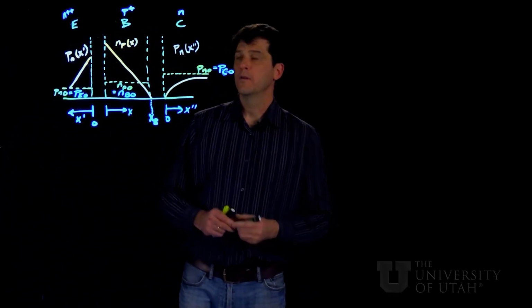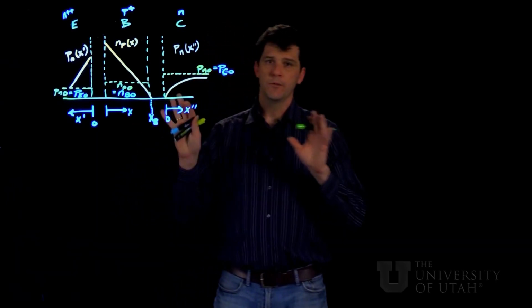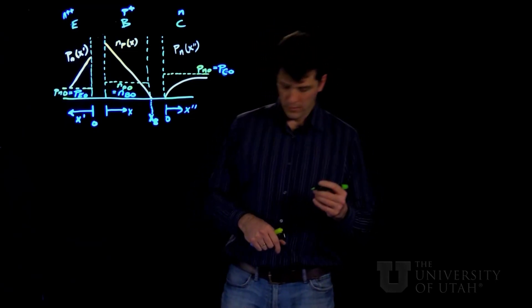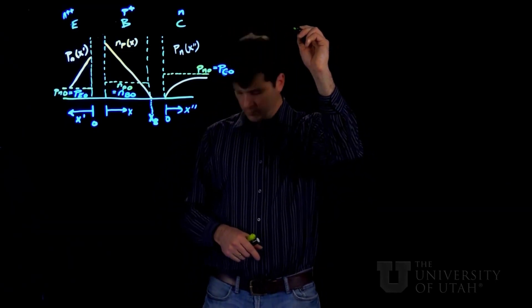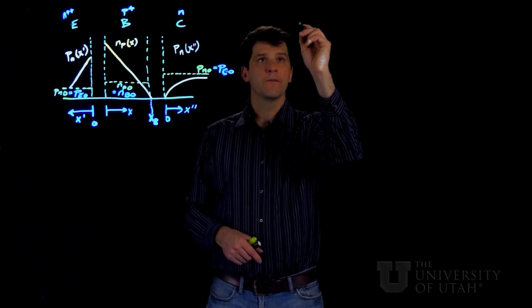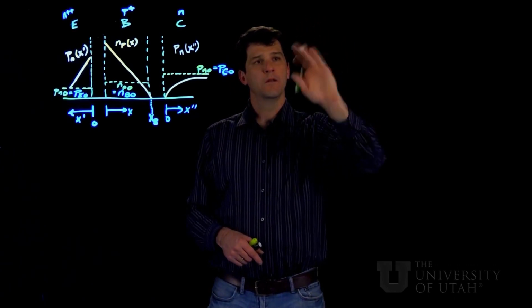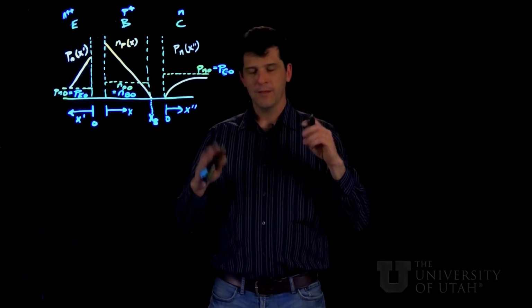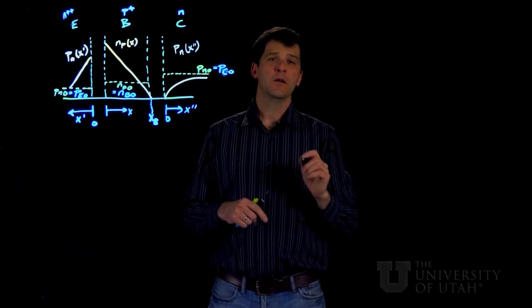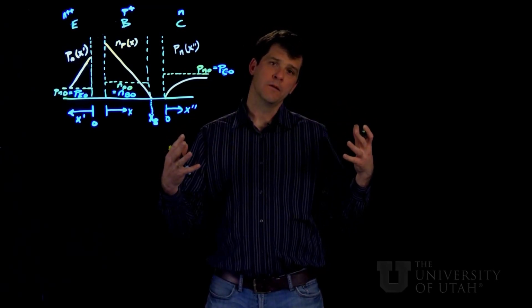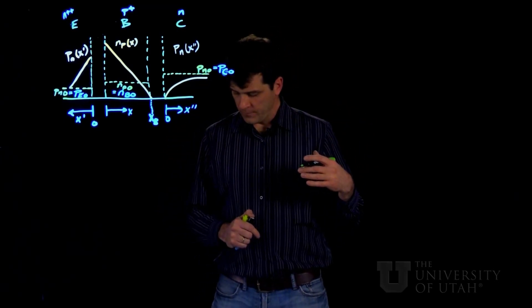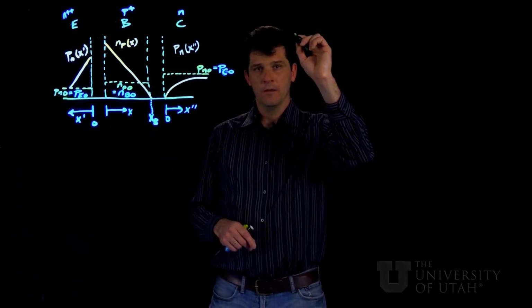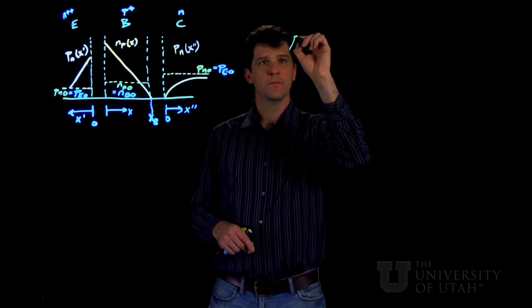So because each of these are PN junctions and we're looking at ideal behavior and injection currents, in each of these regions we have to satisfy ultimately the ambipolar transport equation, but under the low injection approximation and the doped semiconductor approximations, we can reduce it down to the simplified form.